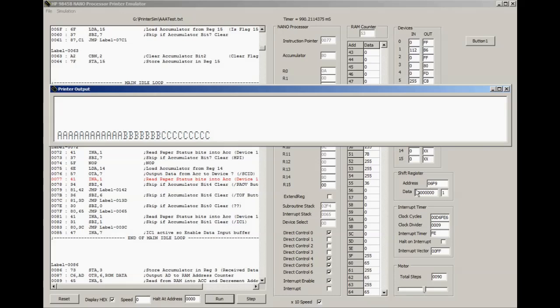We've got the hardware we can refer to with a logic analyzer, and then we can analyze exactly what each part is doing in the simulator. And so I can really test them side by side, seeing how the hardware deviates from this simulation, and hopefully that will be a very quick and easy way of identifying where the fault is.